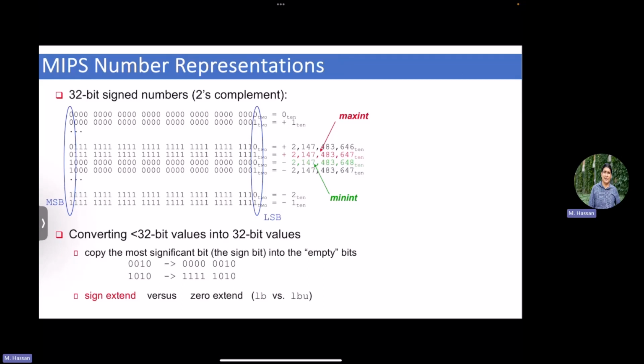Then set if less than immediate, and unsigned, and then the U extension for RISC in general is referring to unsigned operation. Okay? And then I also need to support the logic operations, NOR, OR, ORI, and the I, as we know today, is the immediate value, right? And you also need to support the usual arithmetic operations: addition, subtraction, multiplication, and again, signed and unsigned.